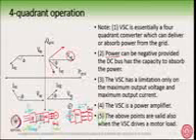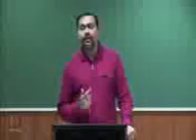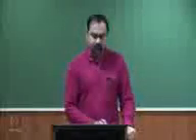But suppose you have a motor here and the motor is regenerating, so you are putting the energy back and it will get pumped into the capacitor, and the capacitor does not have the capacity to feed the energy back to the source. Here is the source. It will not be able to do so because of the diode bridge rectifier. We will see a solution for this in the next slide, if you replace the diode bridge rectifier.